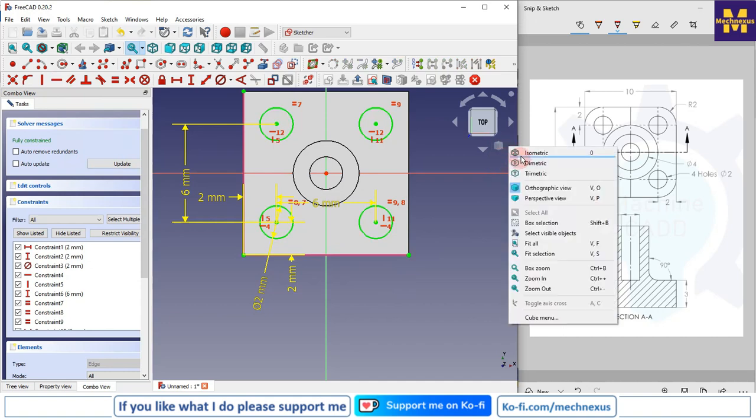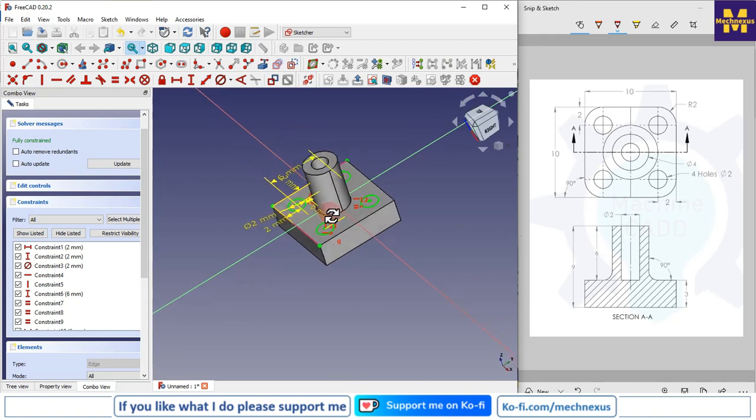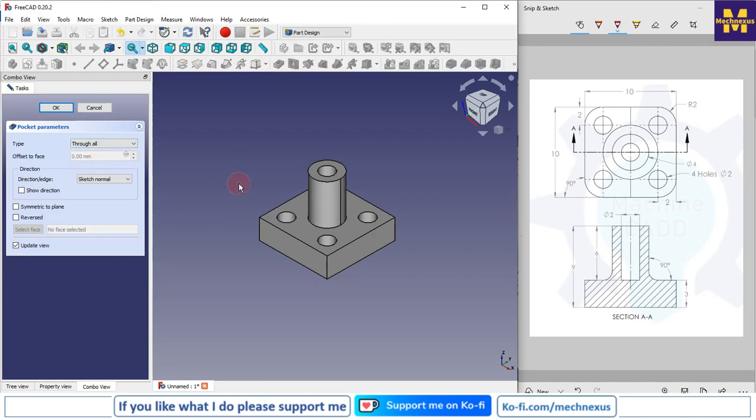Now I will switch to the isometric, and we can see that all 4 holes have been fully constrained. So I will come out of the sketch and go for the cut, and from here I will select through all and say OK.